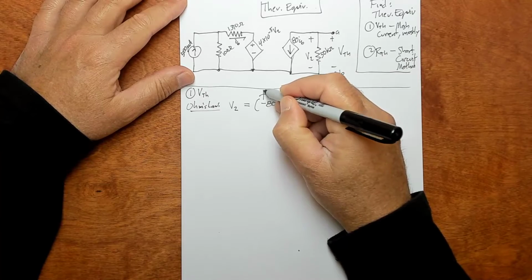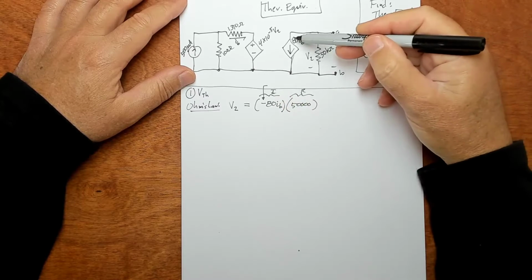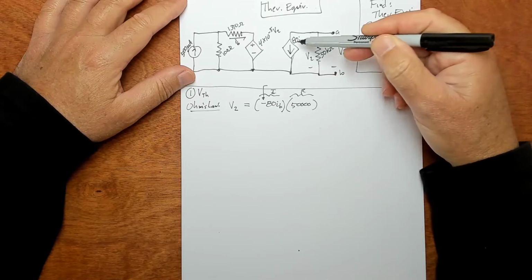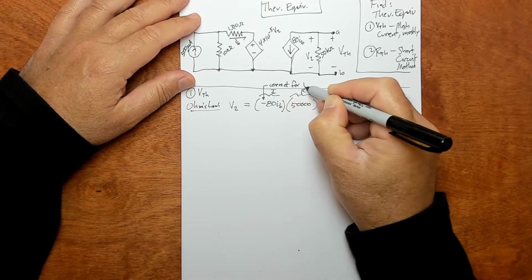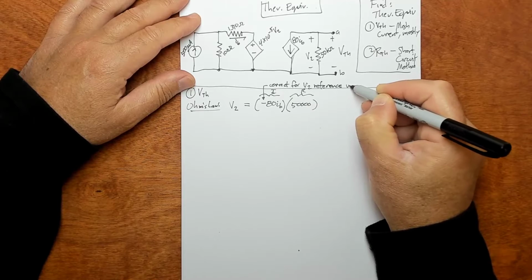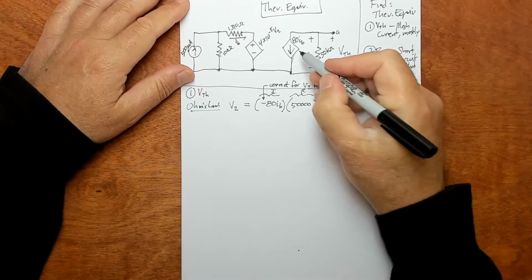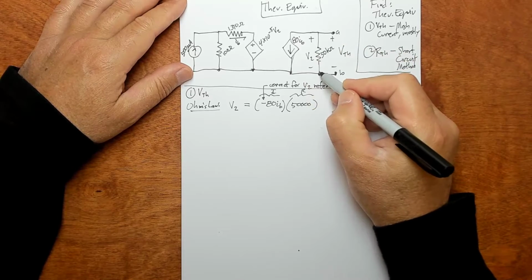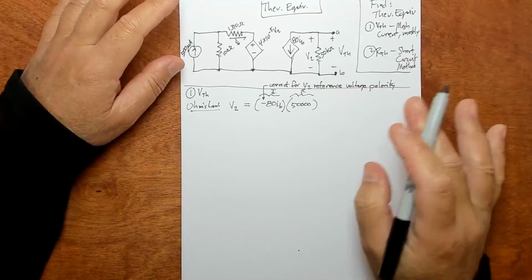So that's another weirdness. This comes from the fact that the voltage drop generated by the actual current direction is opposite of our reference. This is to correct for the V2 reference voltage polarity. We just have to correct for it because 80 I beta is going from the bottom to the top through here, which would generate a plus-minus polarity, which is opposite of what we have labeled. So that's just a little weirdness that you have to correct for.